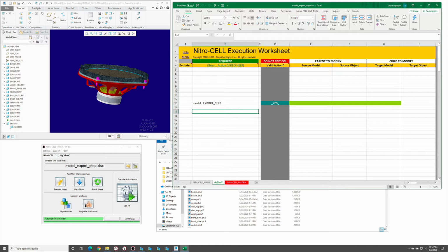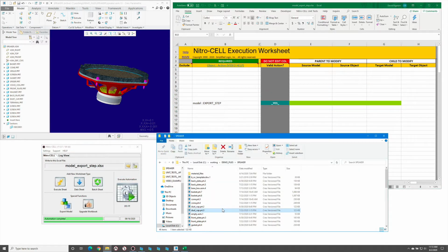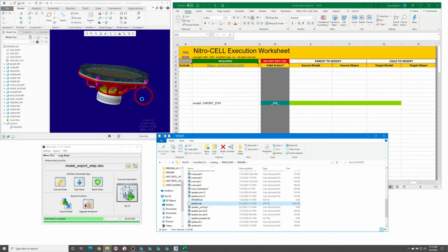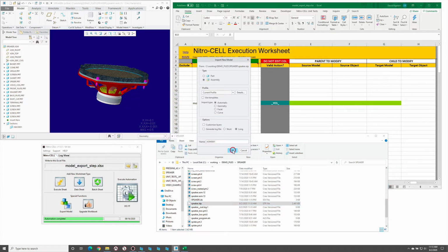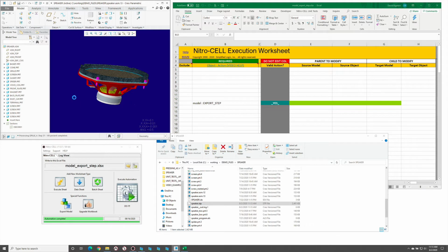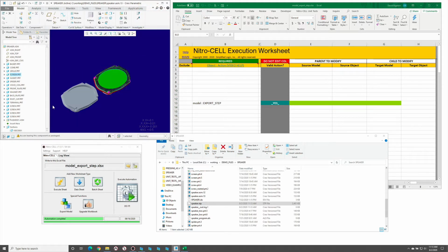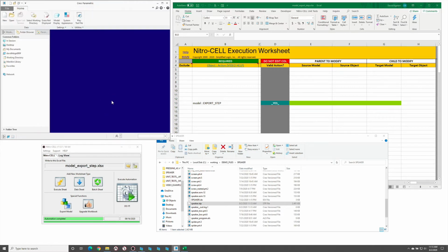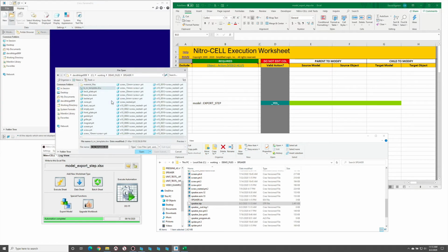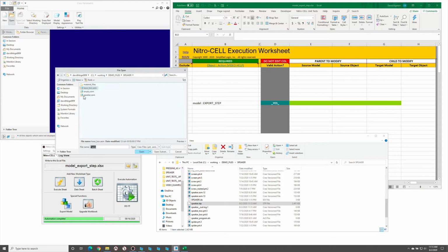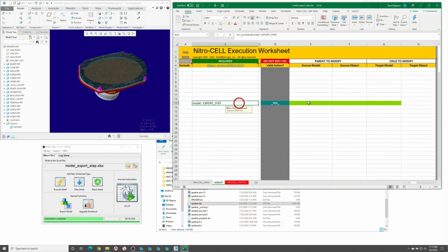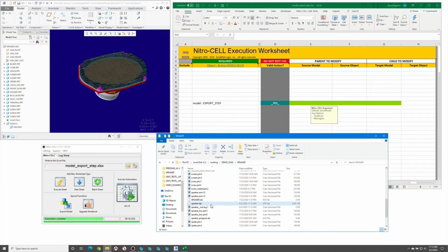So if we run this just as it is, you'll notice that the step file has been generated down here as a single file. So the current file that was in session is what was generated. I'm just assembling this back in so we can confirm that it's been generated correctly. And you can see that, in fact, here is our original, and then here is our step file that's been re-imported. So I'm going to erase memory, and let's open up that speaker again. And now let's do something a little bit more interesting with this.